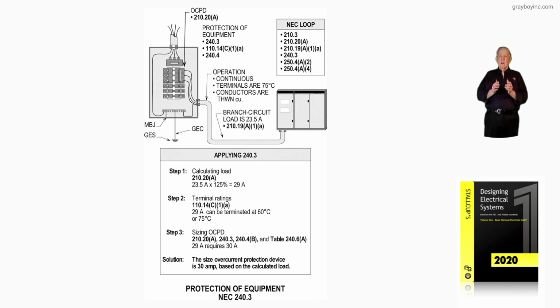without the manufacturer listing a certain size device. Then 110.3(B) and (C) would take over, and the authority having jurisdiction in accordance with 90.4 would determine then what size device would be used based upon the manufacturer's recommendation. And Figure 9-1 is just illustrating the protection of the equipment, performing a calculation and selecting the overcurrent device.